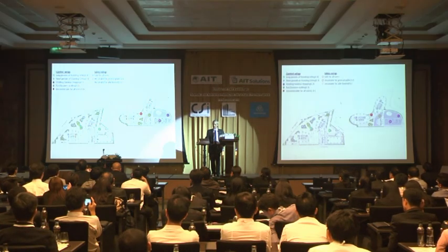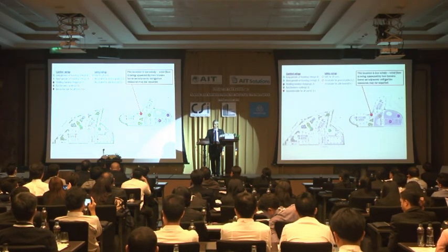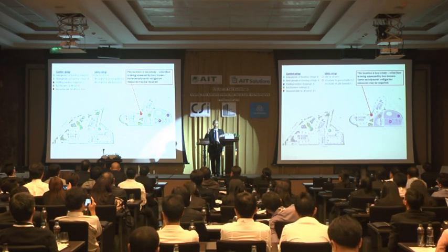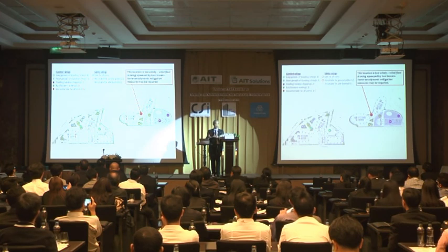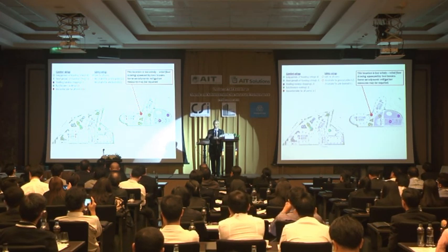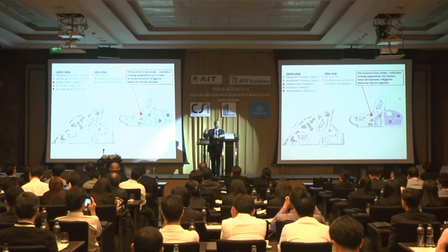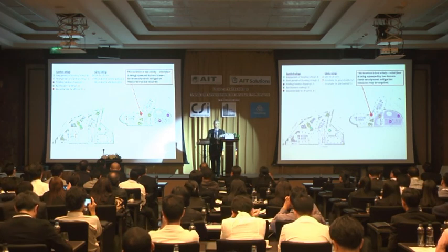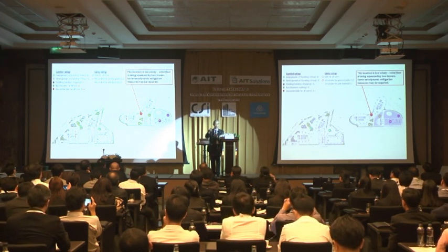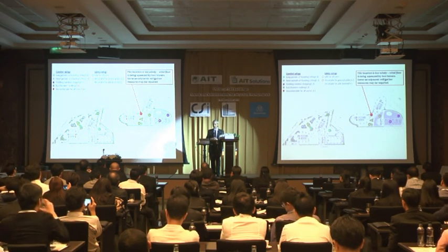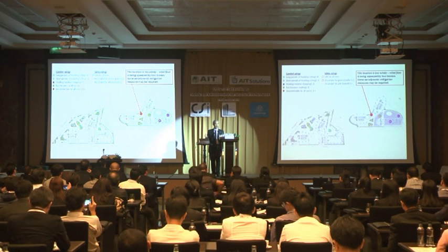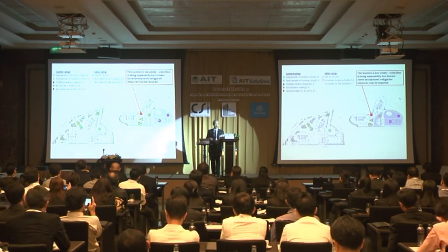Some areas cannot be used for their intended purpose, for example for pedestrians, or for putting an open-air restaurant, because in some areas it may create what we call a jet effect or some local strong wind effect. We can identify these areas by wind tunnel tests, and we can improve them with aerodynamic measures.